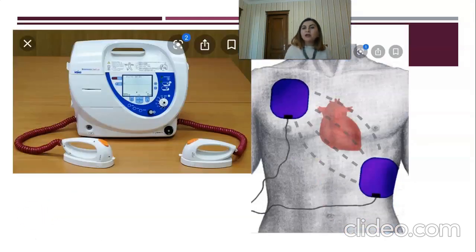And generally our body is sensitive to several microamperes of current. For example, 500 microamperes can be felt by our body. Increasing this current may impact our body, and it can cause different pains and different disorders. For instance, if it's about 5 milliamperes, we will feel pain.